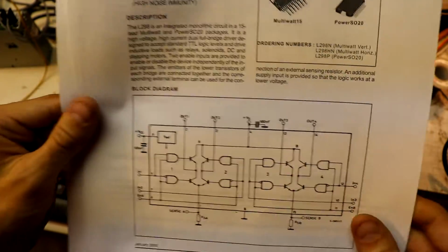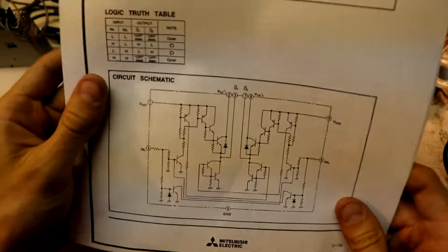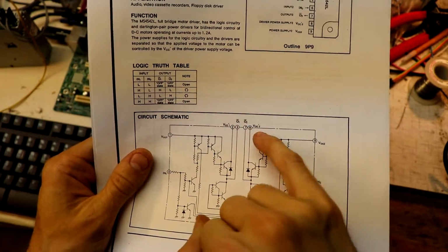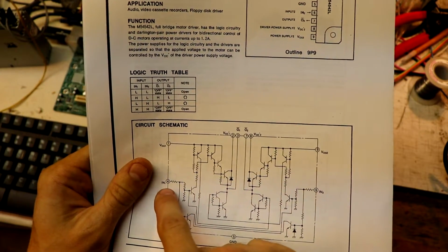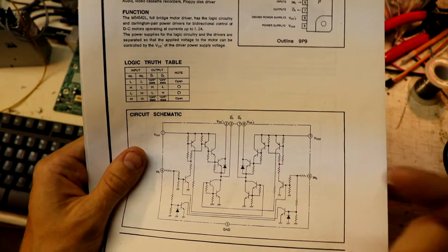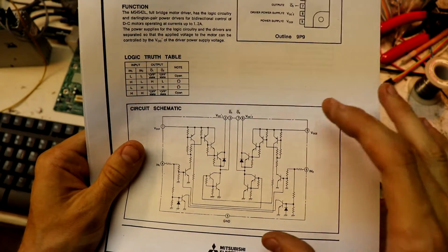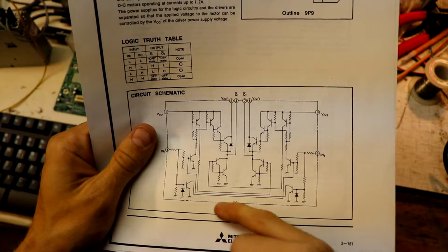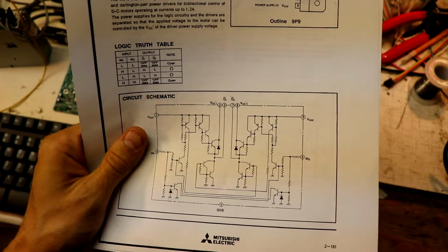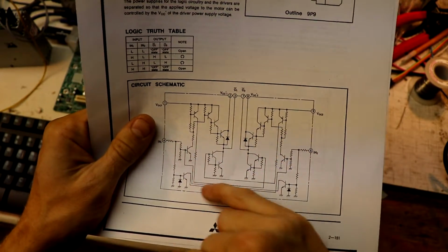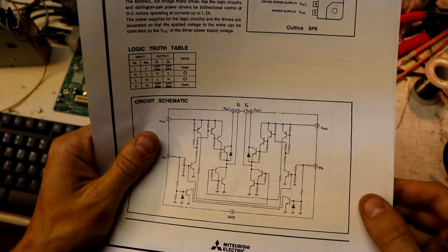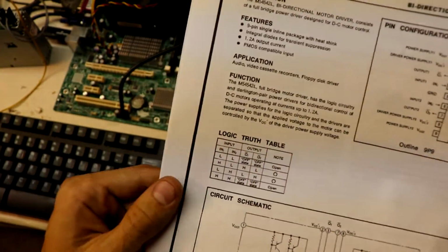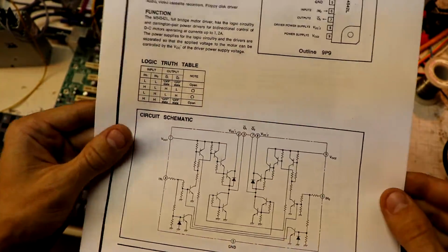That should make sense. Now, the motor controller that I have uses two outputs, and it uses two inputs. And this is just like one full bridge, not a dual bridge. You can notice that we don't have any connections for an enable pin. That's because everything's done internally and they just don't provide that option. And here's the truth table that it runs off of.